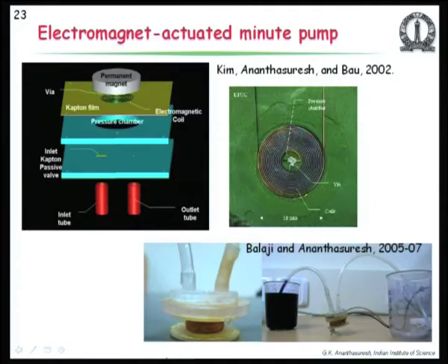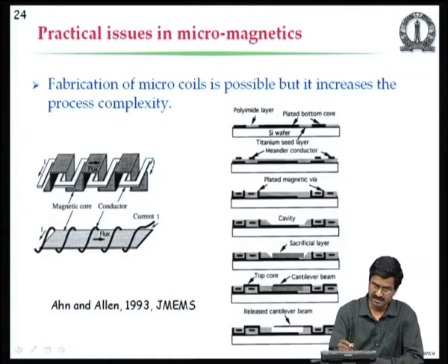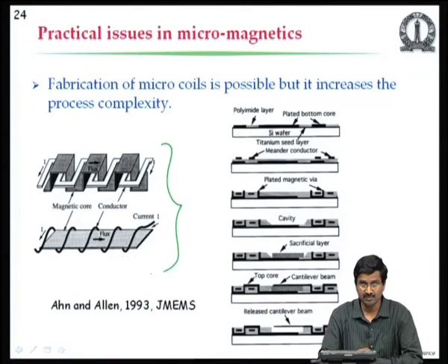So, it does not really scale well, but one can make a lot of pumps and valves and so forth, such as the ones shown here, by using a permanent magnet. That is the key to making magnetic actuation work in practice with substantial force. So, you can actually make coils, as we had discussed earlier, with a trick in the microfabrication process. Topologically equivalent to what is a coil can also be obtained at the micro scale.